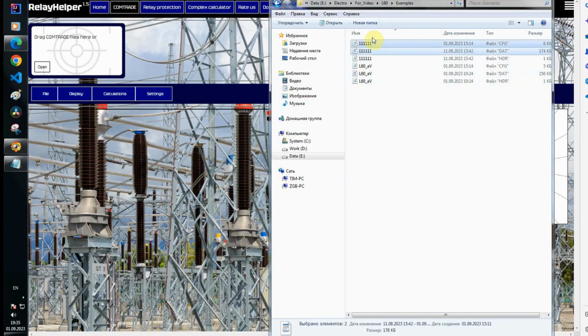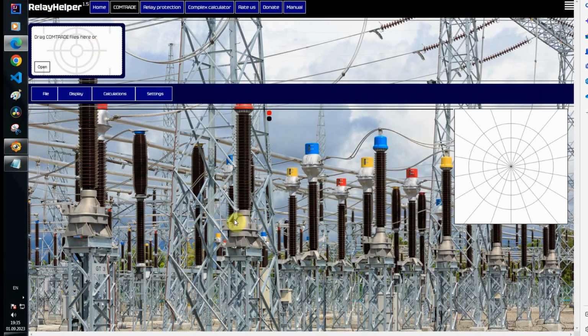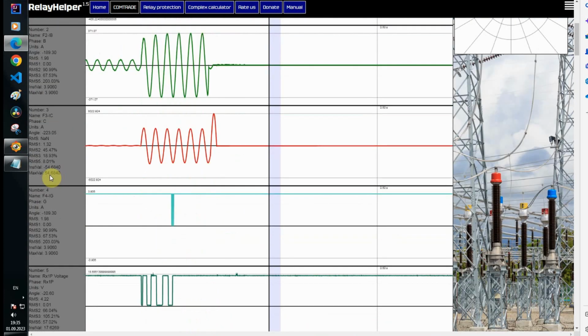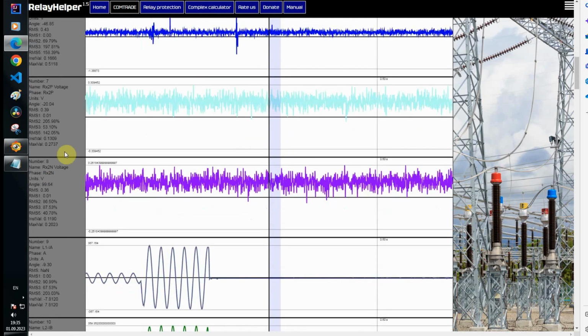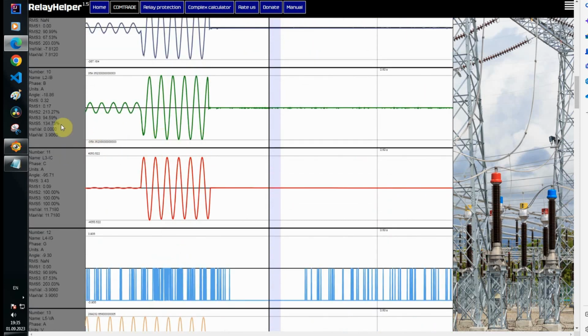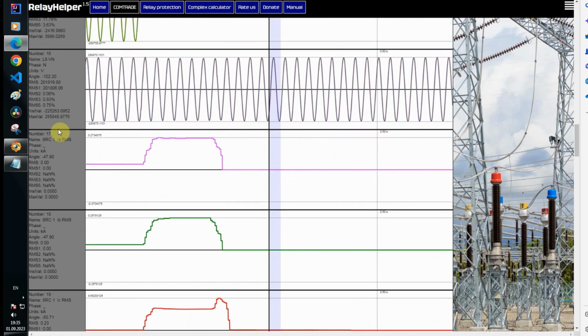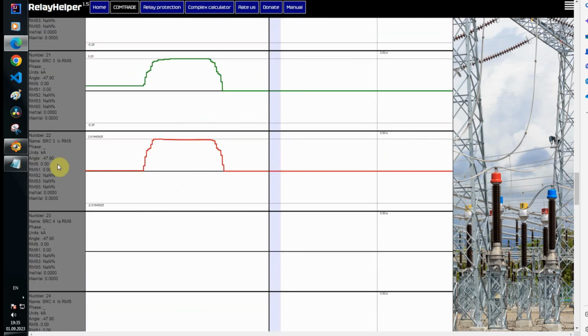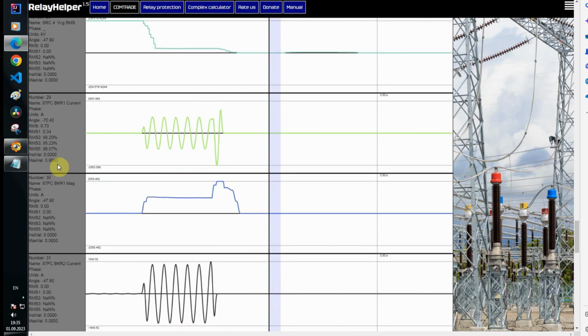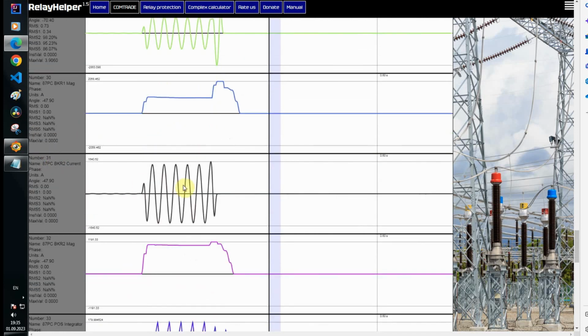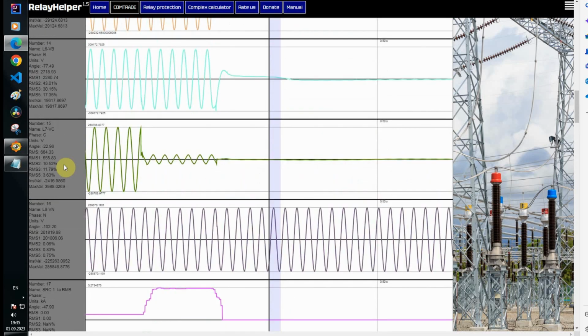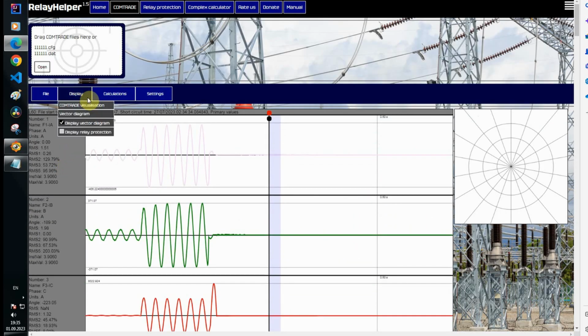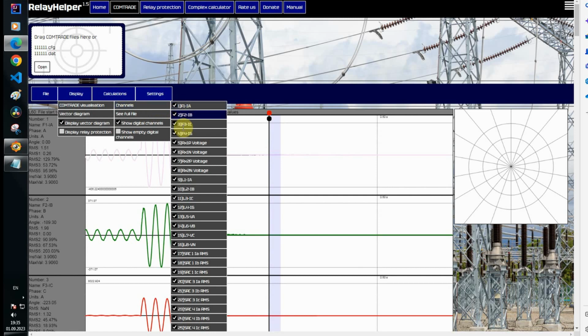Let's look at another comtrade file. Here, a 330 kV line with 2 breakers too. This time both are in operation and there is a short circuit of phase C to ground. Here is the combined signal separately for each breaker. In both cases relays were not very well configured for analysis. It would be more convenient if the sum of 2 breakers was recorded at once.